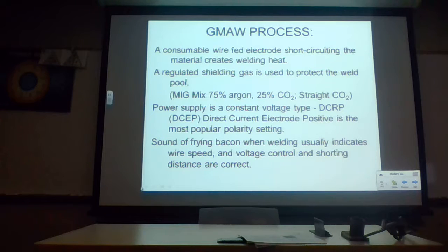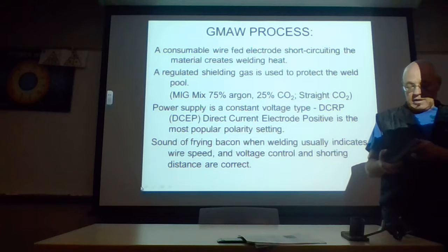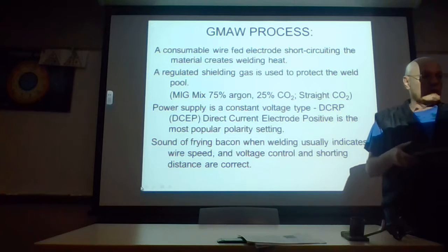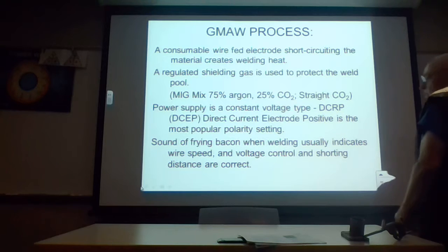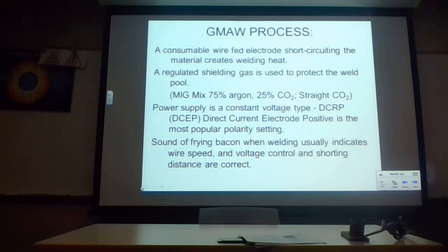One more welding process I want to make you aware of is called MIG welding. This welding process uses a wire feed type of mechanism to short the welding wire against the work surface. Here's a sample of what I did in 1988 with MIG welding. I took that class at City College, and in order to conserve material, they used a wire welder to build up welding bead for a fillet weld. So here's a bunch of MIG welds that have been created on a plate. Obviously, you don't need to have that much of a weld, but to save material, this is what they did. This process is also an electric arc process, and it uses a wire that's short-circuited against the work surface in order to create the molten puddle or the heat necessary for welding.